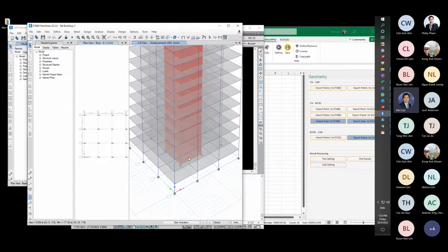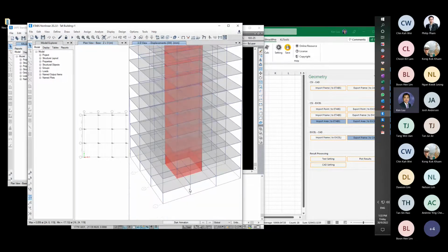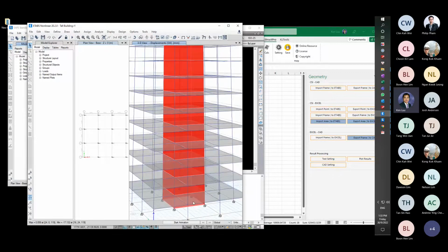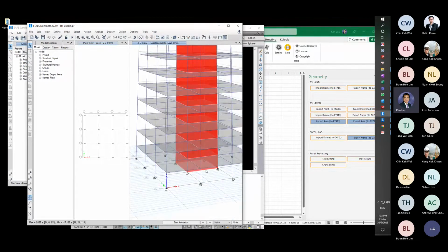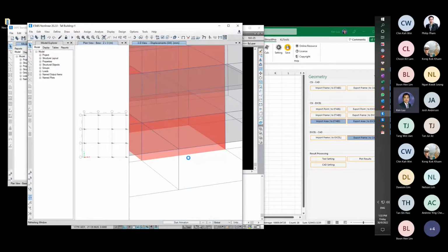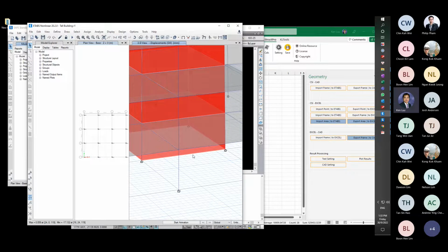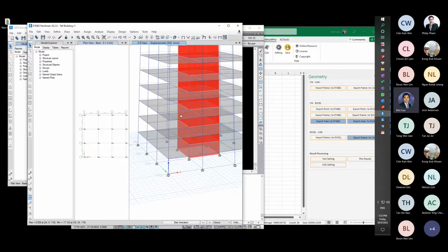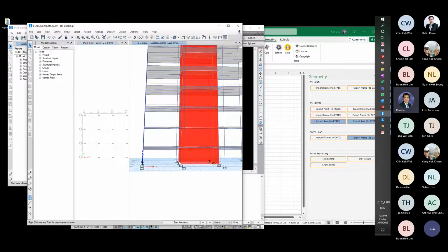That's why, if in your ETABS model you set up the wall mesh automatically, it will define the constraint of the wall edge at the basement, so that all of the points here will be assigned the constraint, so that the load is assigned along the wall. So normally I will ignore that by using the manual mesh, but I will assign the point load to the wall manually.